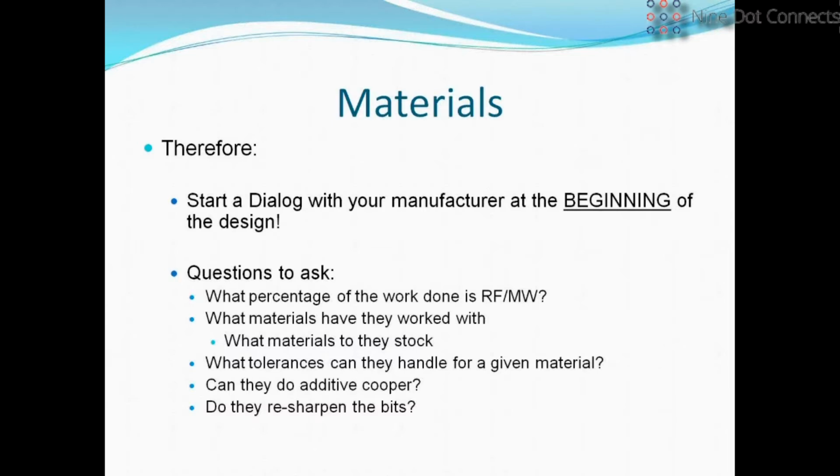For example, some of these materials may work great for 2 and 4 layers, but beyond 4 layers, they can't register it. It's got too much stretch to it, and as a result, they can't register it properly beyond 4 layers. Another aspect of it is what tolerances this material can handle.